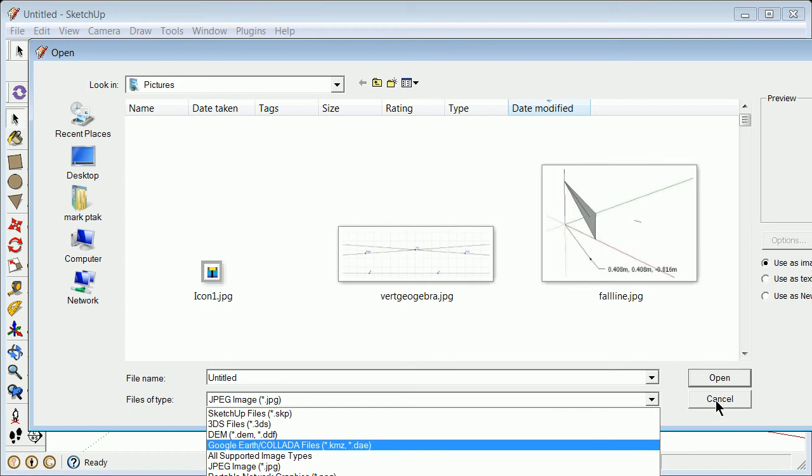All right, so bringing in images, which is really one of the things if you're going to be doing basic animation or basic collaging or mashing up or working with this program, you're going to want to be bringing in images, and you can bring them in either as an image or as a texture. An image acts like its own unit, and a texture attaches and kind of paints an object. I would suggest for now that you might want to experiment with both, but using it as a texture might be better for just base presentation. So you'll see how that goes, and we'll see how that works a little bit here.